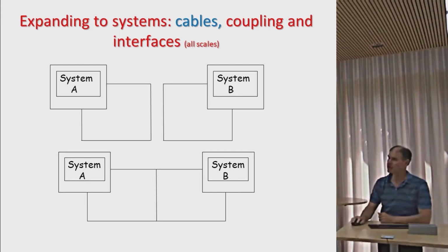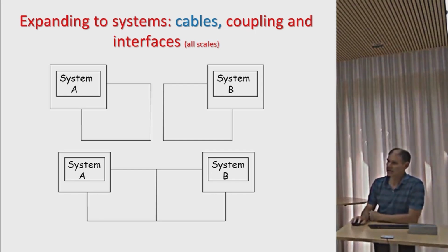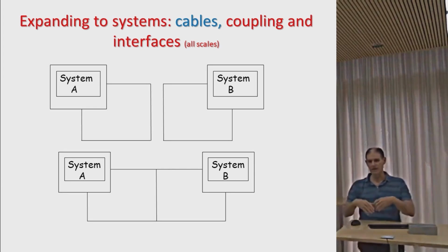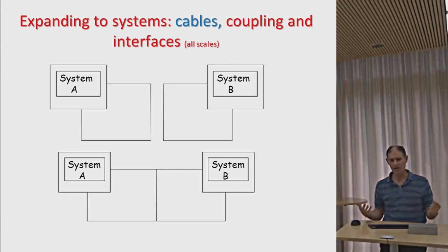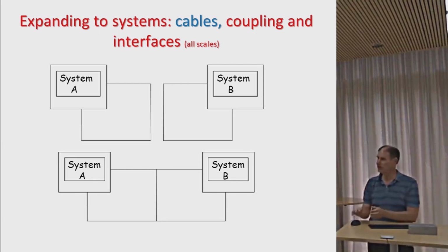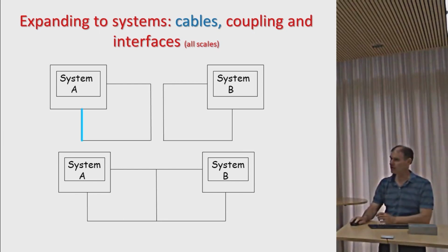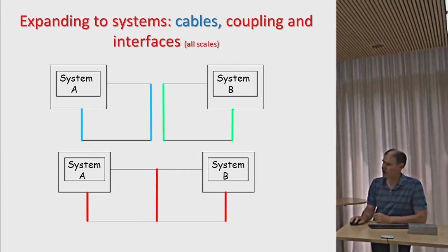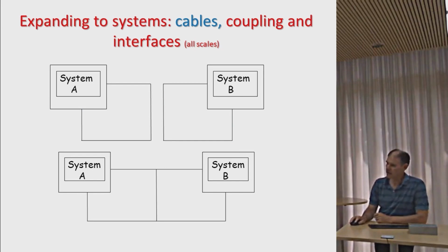And you'll discover that some electronic activity in system A couples into system B. If you then try and save wires, and on an aircraft, for example, you've got maybe kilometers and kilometers of wiring systems, and you want to make the aircraft lighter, you might decide not to have 4 wires, as we have here, 1, 2, 3, 4. You might decide to only have 3, and you share a wire. And an experiment which we can do shows us the consequence of sharing wires.